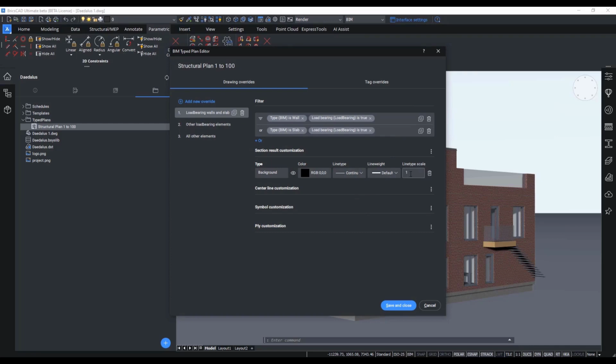Besides the different options which I demonstrated through the pyramid diagram, we have two more options: Override Hatch and Apply for Plies. Override Hatch allows you to specify how an entity's hatch would appear in place of the default hatch pattern already defined within the physical materials library.